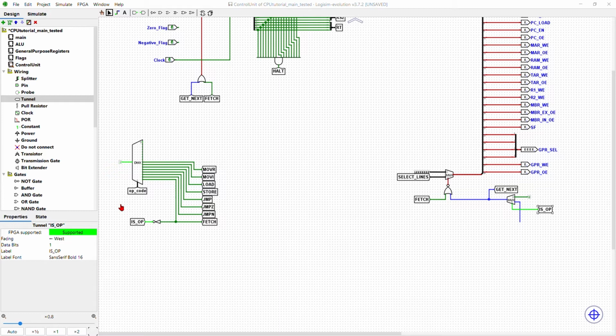So now we are going to actually implement the instructions. Right. So to do that, we are going to create a little circuit for counting. How it's going to work is you're going to have a latch, right? You're going to have a latch connected to a counter. Now, since this is a CISC CPU, a single instruction executes in multiple steps, and you want to be able to know which step you are on. So to do that, you are counting. You know that on the first step I should do this, on the second step I should do that, etc. So you're going to have a counter, but you wouldn't just want the counter to keep counting. You'd want the counter to count based on the number of steps for that particular instruction. And for each count, you'd want to change the select lines because different steps do different things, right?